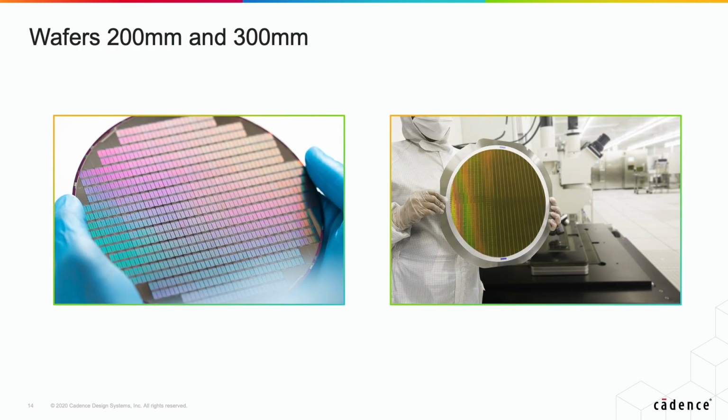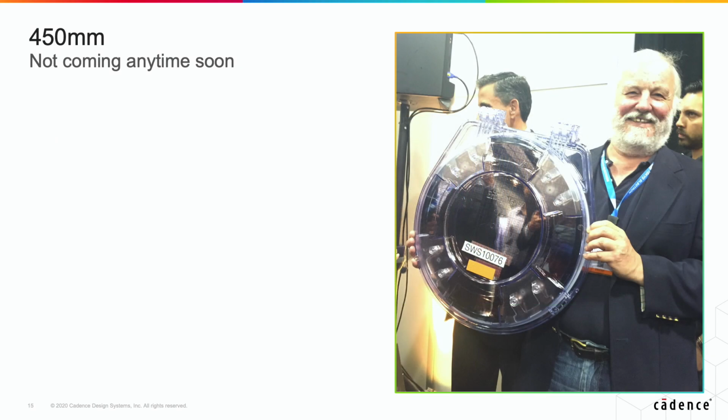So we don't actually build one chip at a time. We build them on wafers, and they're either 200 millimeters, which is 8 inches, or 300 millimeters, which is 12 inches. So here's a real wafer. It actually looks like a dinner plate. It's silicon. It's quite thin. This is Tom Kwan at TSMC's awarded wafer for 20 nanometers. So this is a 12-inch, 20 nanometer wafer.